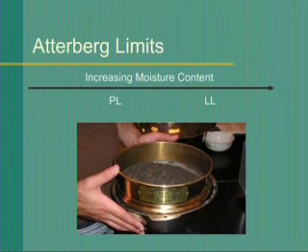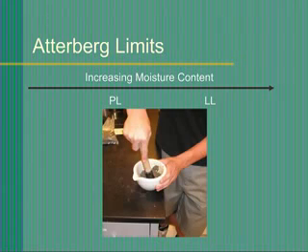If the soil contains significant amounts of sand or gravel, we must pass the soil through a number 40 sieve to remove the larger sand and gravel particles before performing the Atterberg limits test. However, in sieving the soil, it is important that we don't remove silt and clay lumps with the sand particles. Therefore, sample preparation is needed. The soil must be dry enough that you can sieve it, but not so dry that you cannot break up the clay and silt lumps.